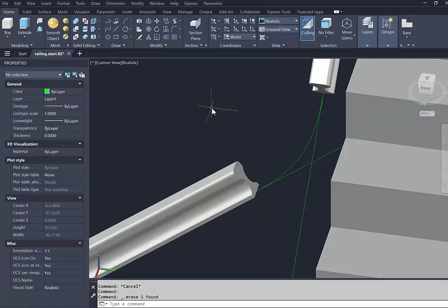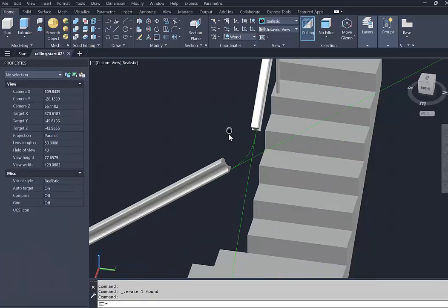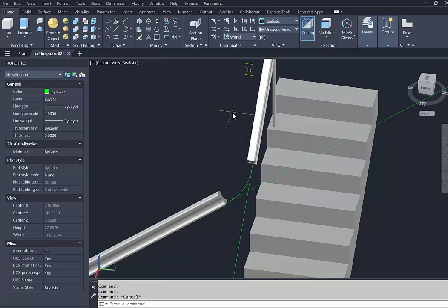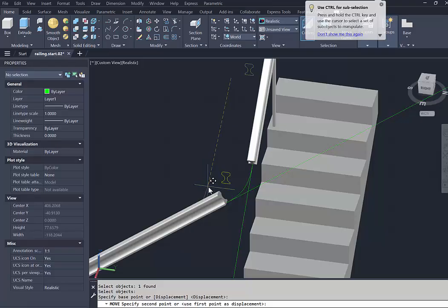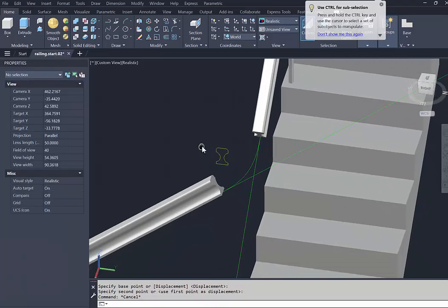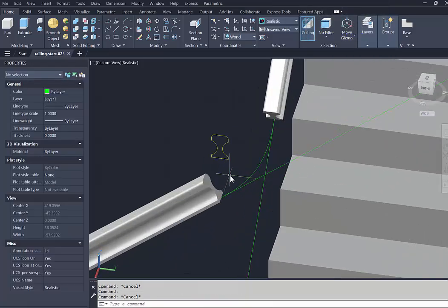And what we'd like to do now is position a cross section in that area. So if I come back here and I'm going to just move this in here, let's say this closed polyline, which is the cross section of the railing, and I'm going to use the align command, ALIGN. You could use align 3D as well. It's a little bit different, but does the same thing.